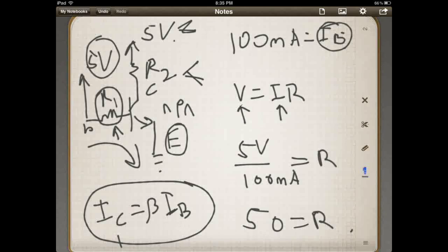Maybe you're pushing 5 milliamps on one of them because you really need a lot of current coming through it. This one's a fairly small one, but let's say you've got a big beefy one. It needs like 5 or 10 milliamps, and you've got 7 of them. You've got 70 milliamps on one port. The port on a PIC microcontroller is only good for 90. So that's what I mean. They're kind of current hogs.